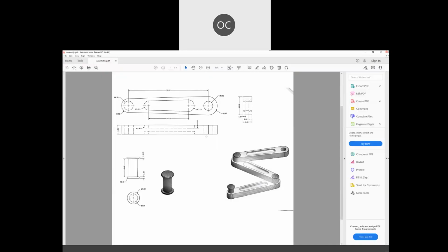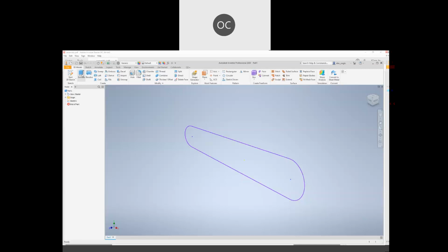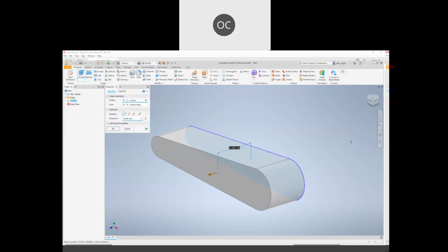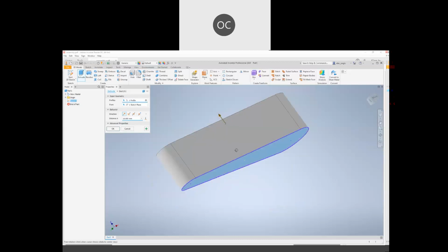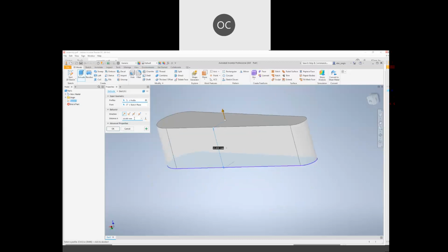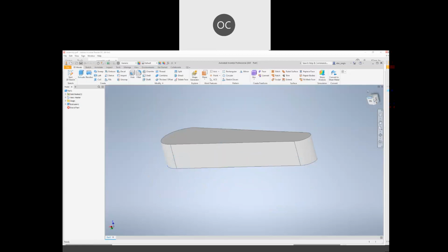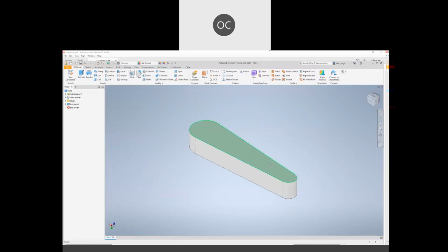So we are going to do extrusion, extrude this profile to the height of 6. So please go to extrude. Since you only have one profile of selection, it will be selected automatically. So the distance will be 6. Distance will be 6. So once you have done that, then that will be your...